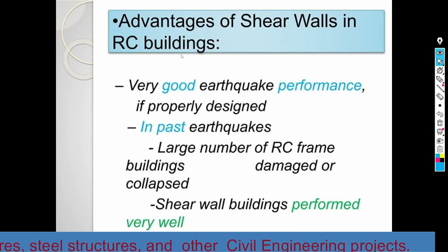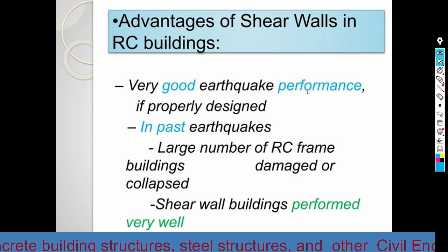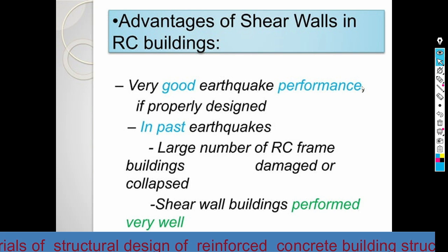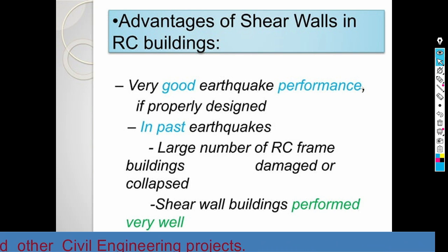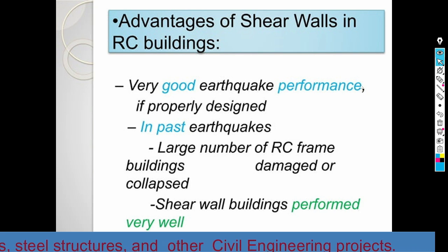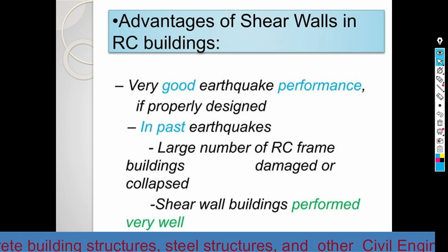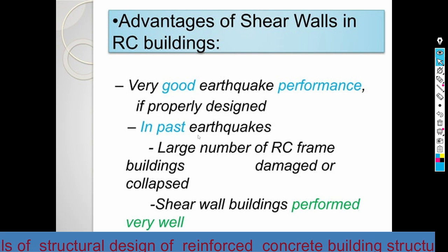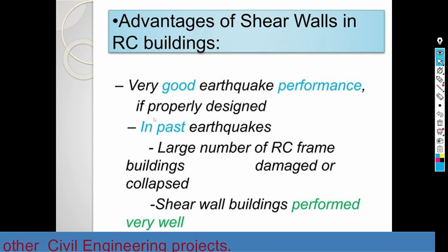And the advantage of shear wall in RC building is very good earthquake performance. So whenever there is a seismic or horizontal force, or whenever there is a possibility of increasing the total height of the structure, we need to use shear walls.